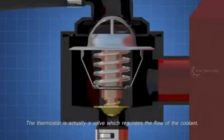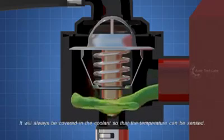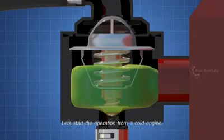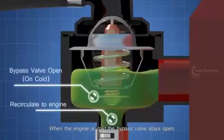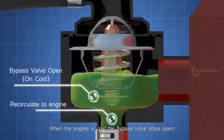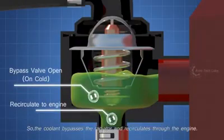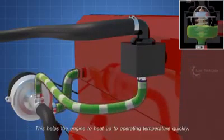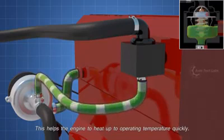So, finally, let's get into the working, starting with the thermostat. The thermostat is actually a valve, which regulates the flow of the coolant. It will always be covered in the coolant, so that the temperature can be sensed. Let's start the operation from a cold engine. When the engine is cold, the bypass valve stays open. So, the coolant bypasses the radiator and recirculates through the engine.